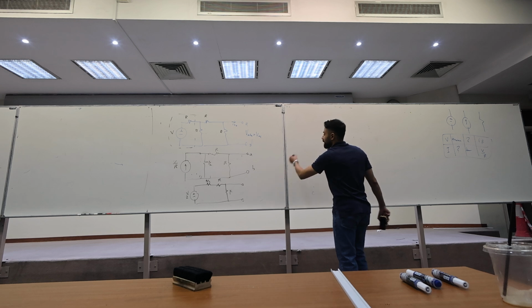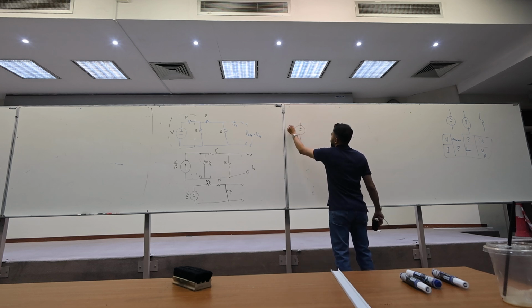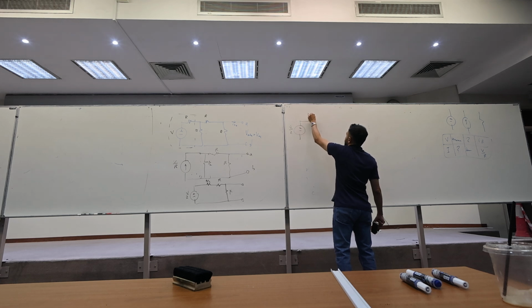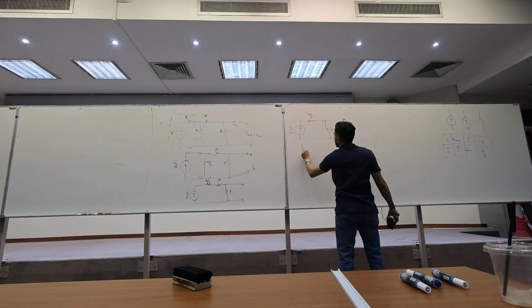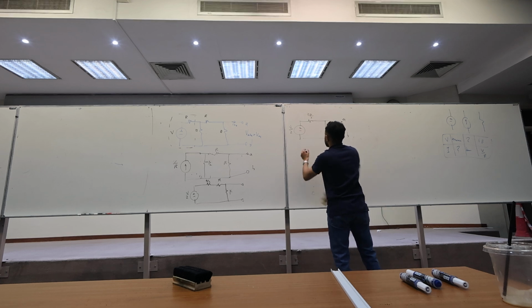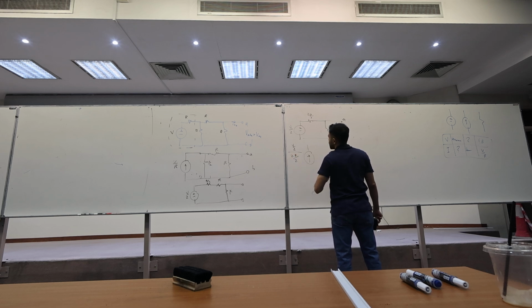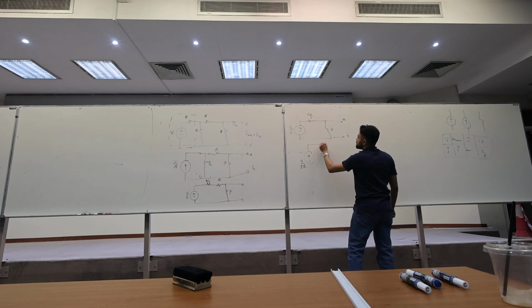So, simplified, it will be a voltage source of V over 2, 3R over 2, another R, you still have A and B. Another source transformation, what you will have? Current source of V over 2 divided by 3R over 2. Right? So it will be V over 3R. Right? Yes. And then you will have what?